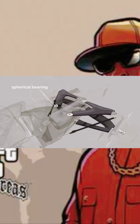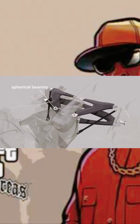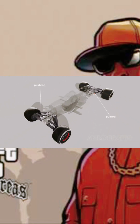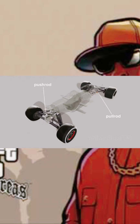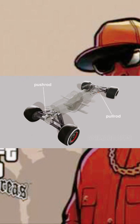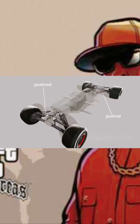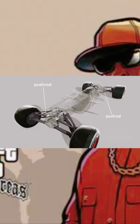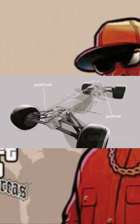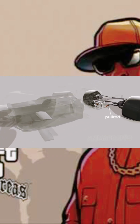At the rear, where engine heat can be intense, spherical bearings are used. The push or pull rod is where the action happens. Our model has push rods in the front and pull rods in the back, which simplified just indicates how the system is mounted to push or pull connected suspension parts. If parts can be mounted down low for a lower center of gravity, all the better.